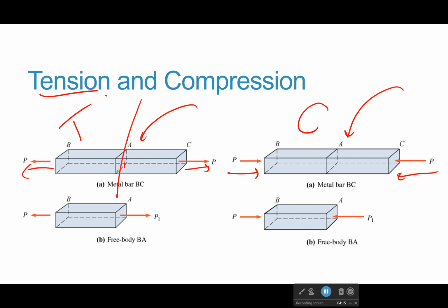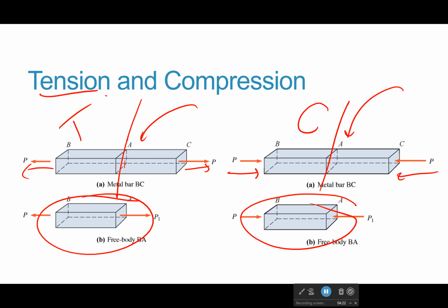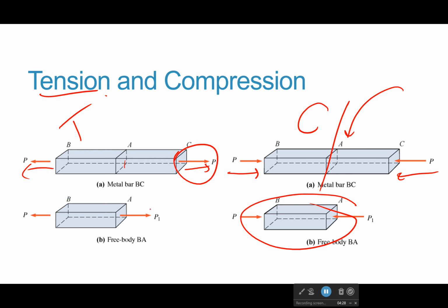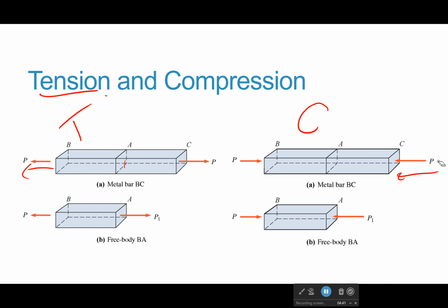If I cut it, hi-ya, I'm a ninja, that little section in there will also be in compression or tension, whatever the other one was. And also that force that it was feeling on the outside is felt inside as well. I could cut there, there, any particular point I want to. They're all feeling the same load. That's important. The load doesn't just disappear. It's the same load and it's felt all the way through the material. So if the material fails at any point, that's not good. We don't want that to happen.